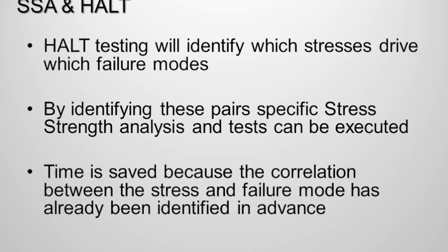So used in conjunction with HALT, HALT will identify these stresses which drive these failure modes. So by identifying these in advance, the stress strength analysis test can be executed with much more focus, can be much better designed. So you can see the theme here in using HALT with a lot of these other tools. What happens is you're able to, in advance, understand the fundamental relationships between stress and failure mode. So time will be saved because the correlation between these is understood in advance. And all these other tools yield much greater results because in designing these other tests or doing these techniques, you've gone into it understanding the product better.